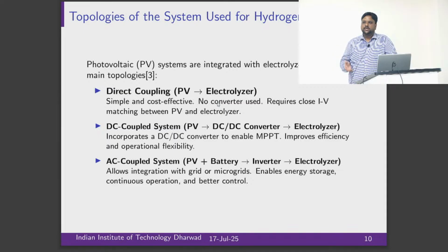Okay. Definitely, even if you generate hydrogen locally, you need to convert to DC. But even at grid scale, where you have batteries or solar, wind, and suddenly you want to have the electrolyzer in between, you will take the common bus. You will connect an electrolyzer at a common AC bus, which you can say is maybe the point of common coupling, where all other sources will be connected.